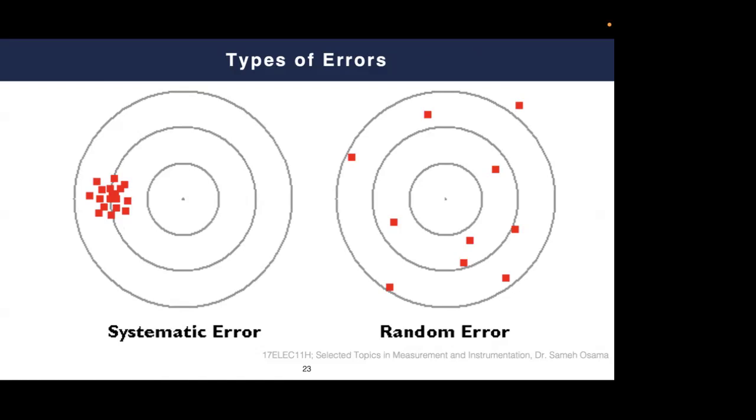Referring back to the example I just mentioned to you related to the load cell, when I use it to measure the mass of an object, we found that this 1 kilogram calibrated weight is reflected on the monitor of the scale as 1.05 kilograms. So if I measure 2 kilograms, it will not be measured as 2 kilograms, it will be measured as 2.05 kilograms and so on. So as you observe, we have some sort of a shift.